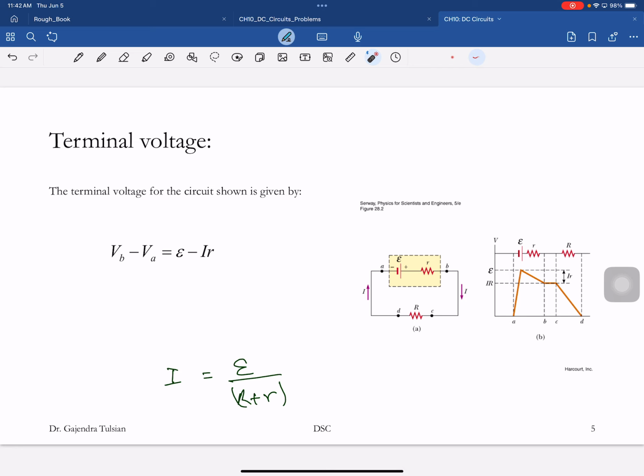All right. Now, the voltage that you see outside the battery, you'll understand this in a few minutes, is when you go from here to there, the voltage changes plus E, and then current flows from a higher voltage to a lower voltage. So the change in voltage across this element is I times R. So E minus I times R, that is the voltage you see outside the battery. So if this was a 12-volt battery, you don't see 12 volts, you see this much less.